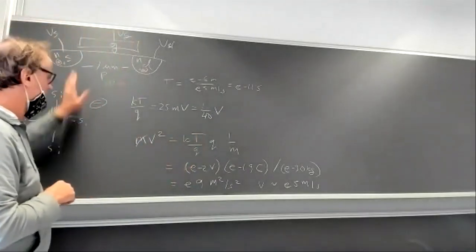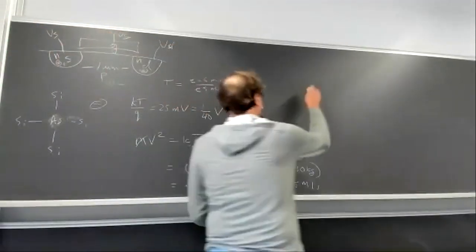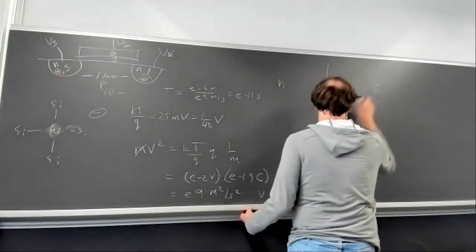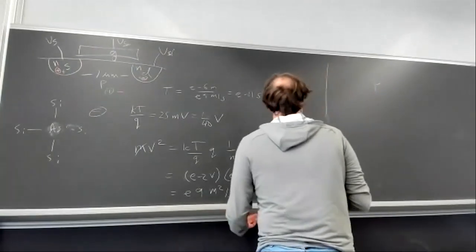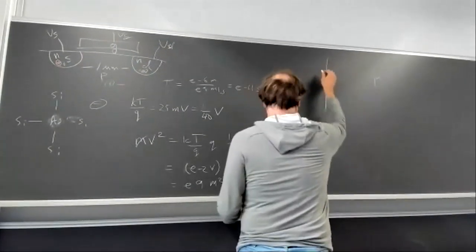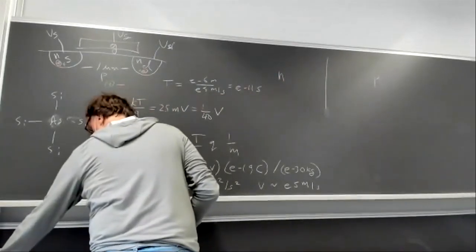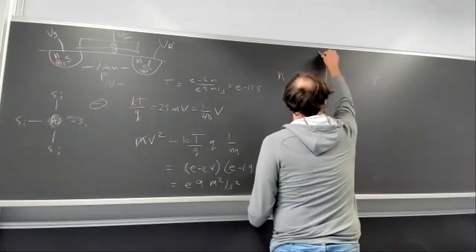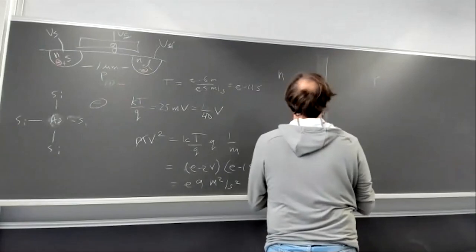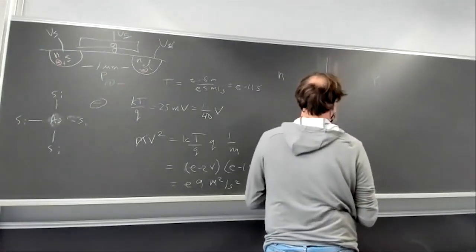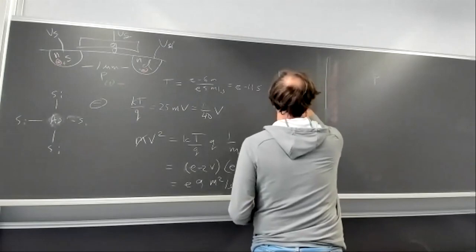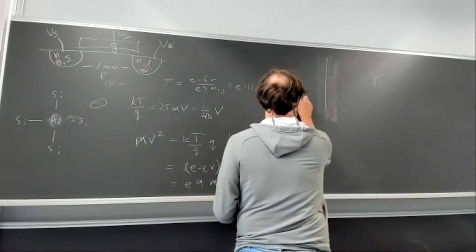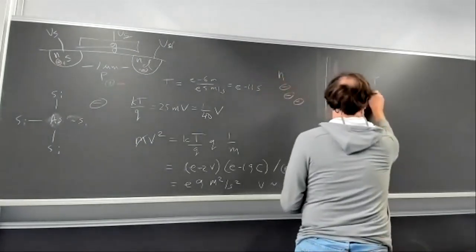So that's why you have to now draw the basic p-n junction to explain this. And you'll see it's really simple in the end. Let's say this is n-type here, and p-type here. And that means, I'll just summarize it here. In the end, you're going to have a depletion region build up. I think positive here and negative here. These are fixed ions that are exposed. And over here, you're going to have lots and lots of free electrons still. Over here, lots of free holes.